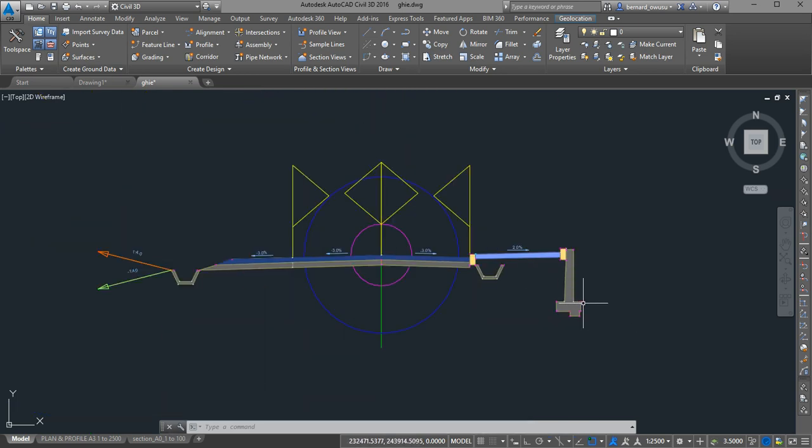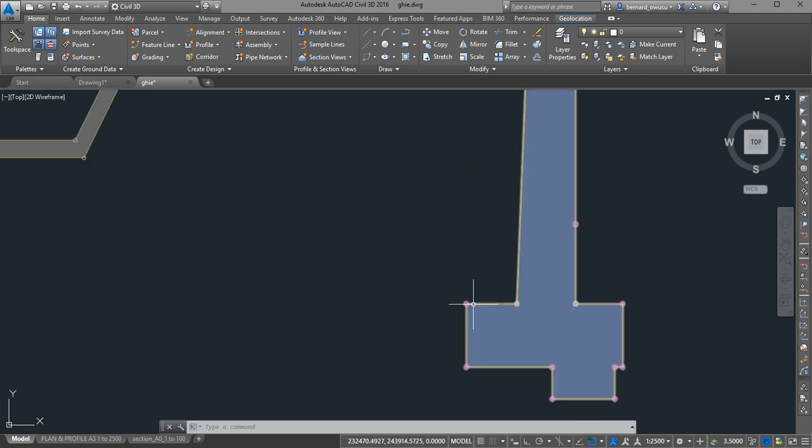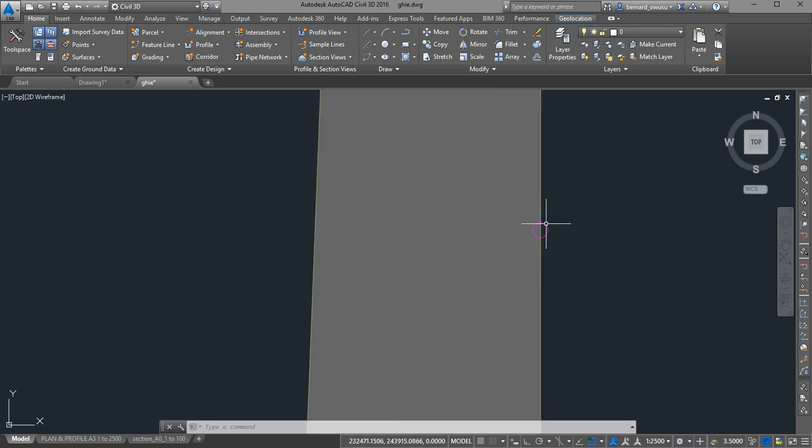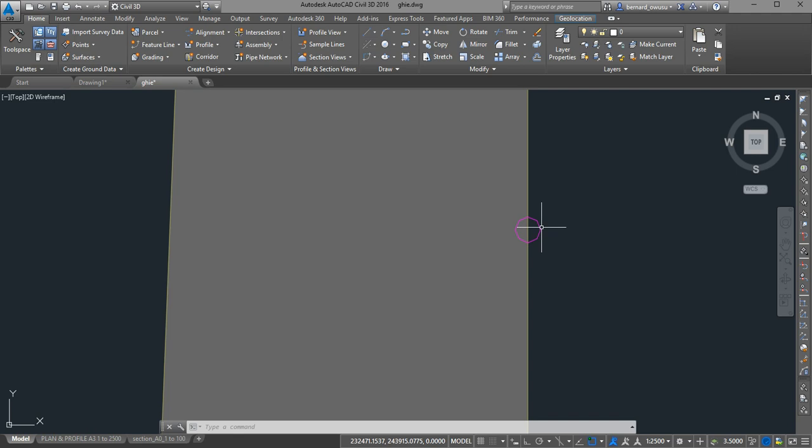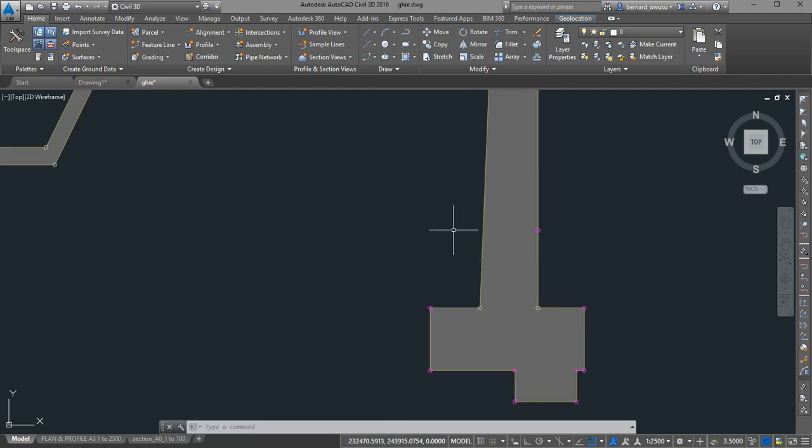So in this case, let's say that once I have it this way, the ground is going to be somewhere. Can you see this button? So it means that this part goes down. This is the ground. The ground level will be somewhere here, and all this will be buried. So after the retaining wall has gone down, what do I want to do to the ground? I want to maybe polish it, or maybe leave it as it is. Depending on the cross section that you have, at the toe here, you may have a toe drain. You may put a drain here. So you have to decide on what you want to do.